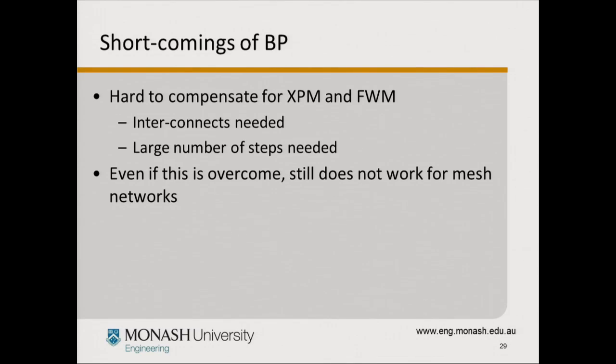So digital backpropagation has a large potential, especially as the power in digital techniques and signal processing is forever increasing, but in order to compensate for cross-phase modulation especially, you need a large number of interconnects and a large number of steps. Even then, assuming that we eventually overcome these issues, which is a big if, this method is still not suitable for mesh networks because the wavelengths can be switched and your neighbors may change.